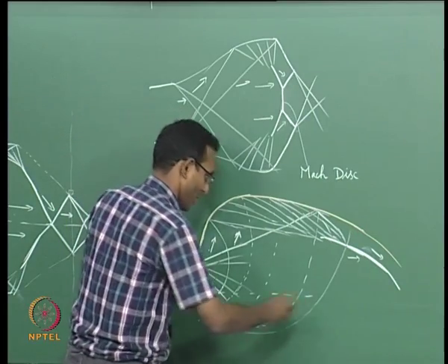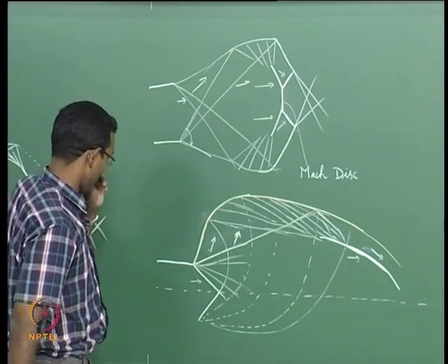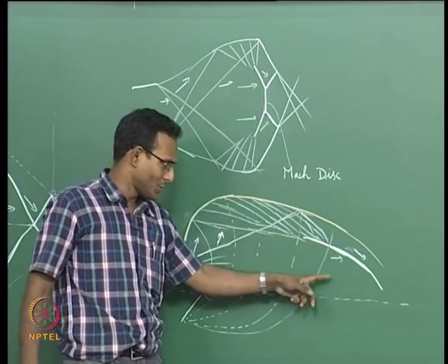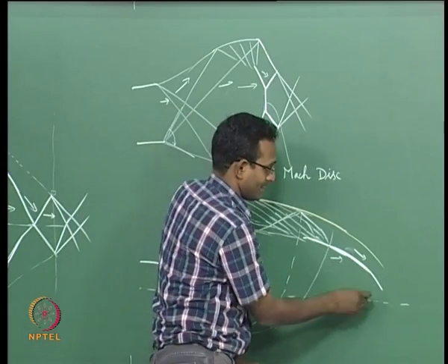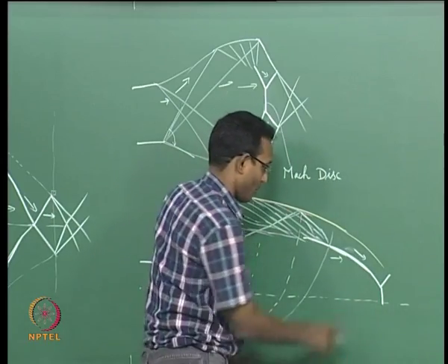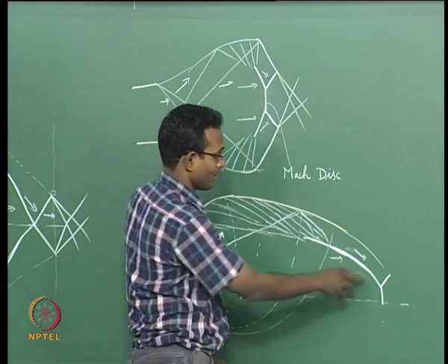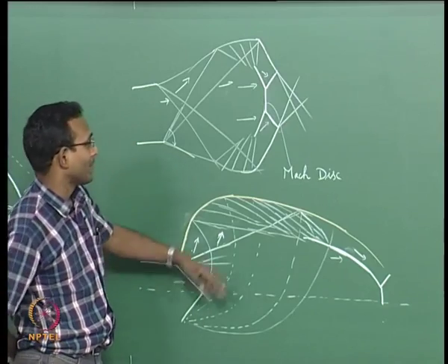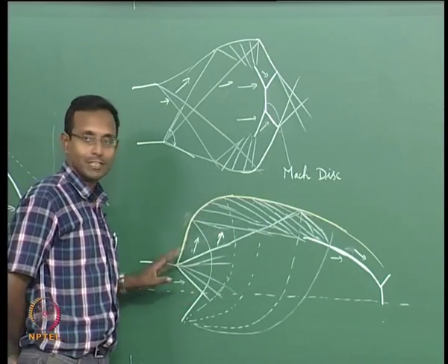Now, I will go extend my axis. At the axis, for this much expansion, if all those expansions come together forming a shock, that shock is typically very strong near the axis. So, when it crosses the axis, it goes through a Mach disk. I am drawing only one half of the thing, otherwise it is supposed to be a disk fully. It forms a Mach disk, and this also happens. This is typically a very underexpanded jet. It has to expand a lot after it comes out. That is the case for this.